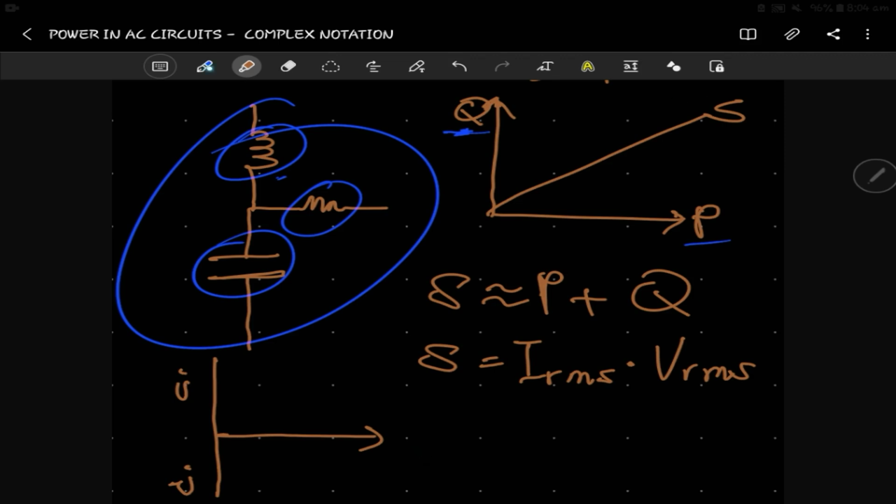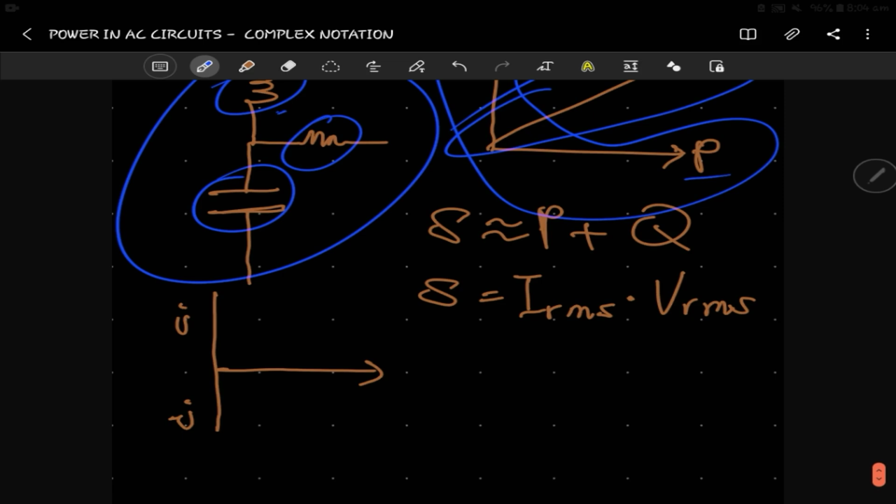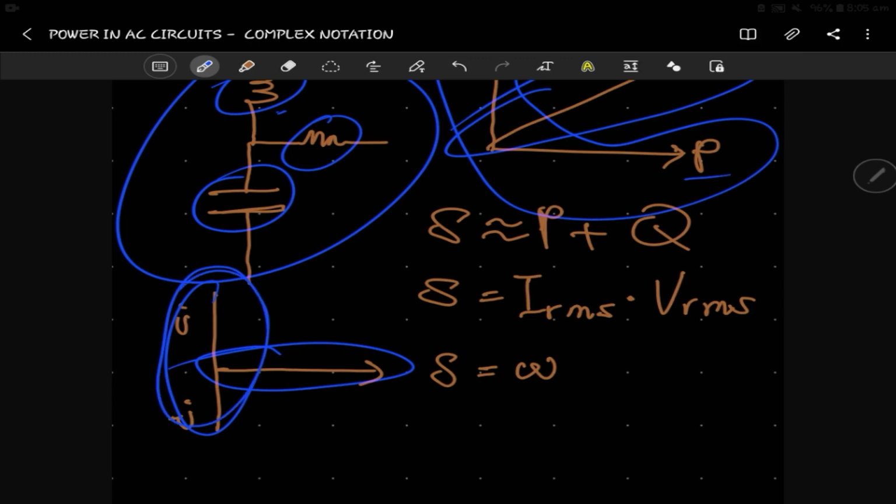If you are trying to represent this whole apparent power, you can still use this, by using the complex form. So we know that we end up getting the apparent power in this form, where we have S, and we have some quantity for the real power, let's say P in watts, for the real part, and the reactive part from the combination of whatever we have here, depending on what we have, it could be plus or minus, and we have let's say Q. And because of this, we have to introduce something to show that it's a complex part. So we have a J.